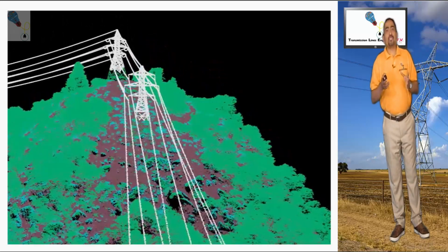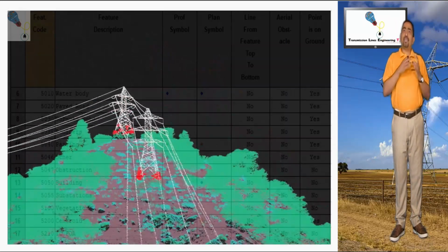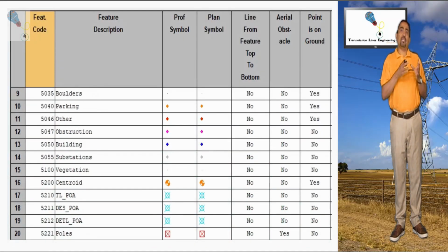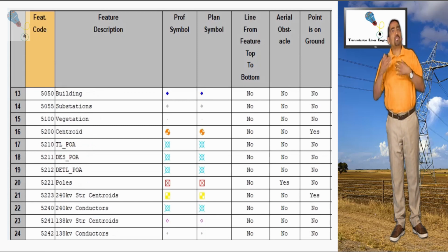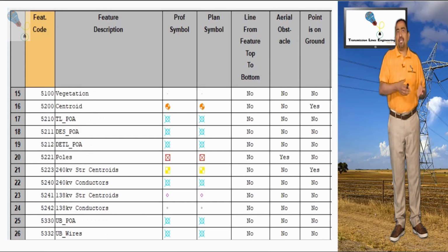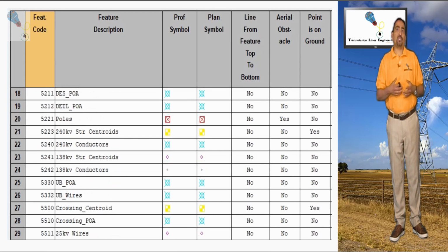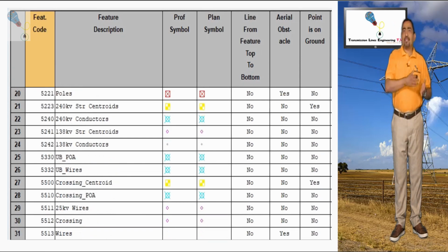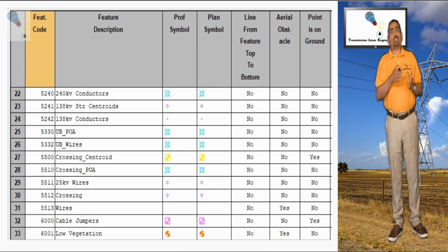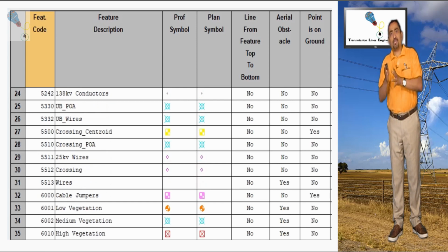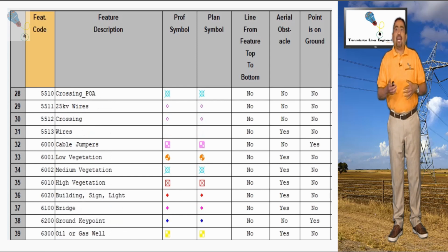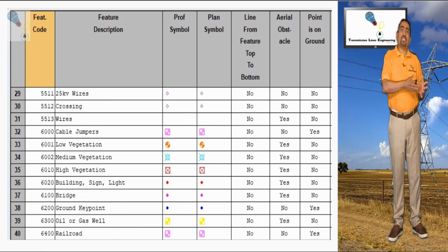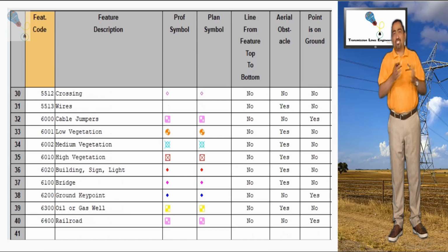For its analysis, an identification code is previously created for different types of points: vegetation, terrain, cables, structures, etc. The analyst will filter these points to assign their respective code depending on what is involved, and assign a specific symbology and color to differentiate them from others.